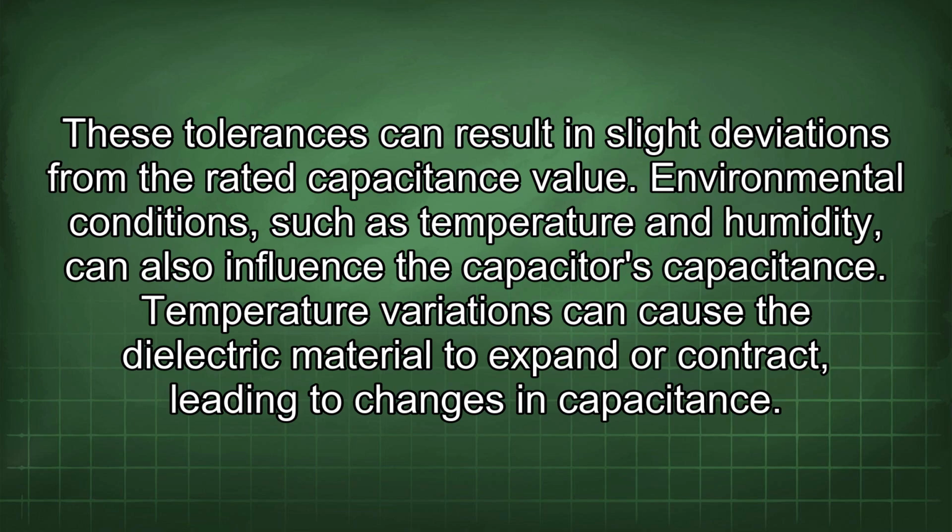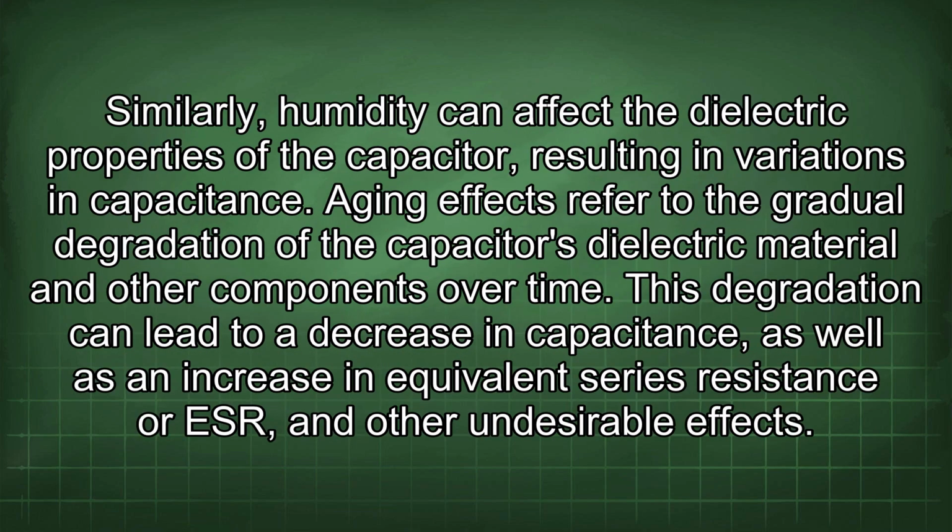Environmental conditions, such as temperature and humidity, can also influence the capacitor's capacitance. Temperature variations can cause the dielectric material to expand or contract, leading to changes in capacitance. Similarly, humidity can affect the dielectric properties of the capacitor, resulting in variations in capacitance. Aging effects refer to the gradual degradation of the capacitor's dielectric material and other components over time. This degradation can lead to a decrease in capacitance, as well as an increase in equivalent series resistance, or ESR,